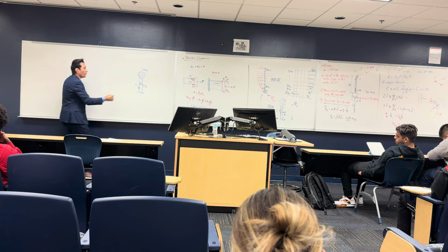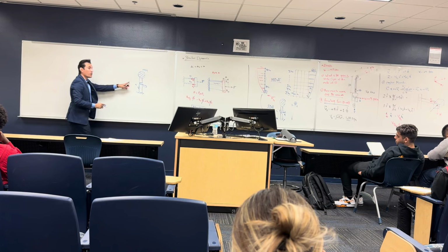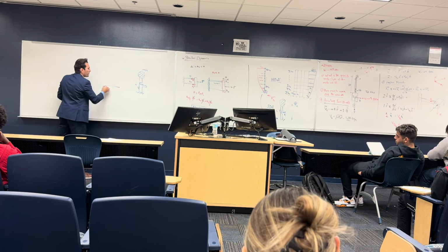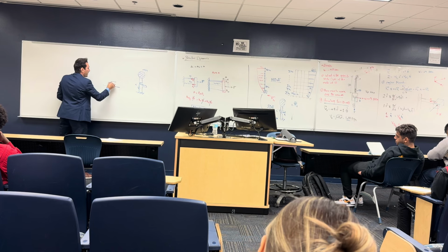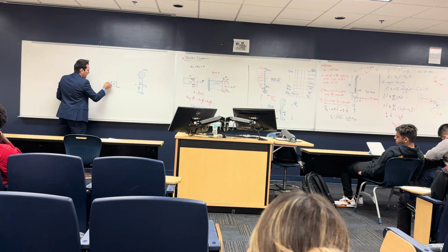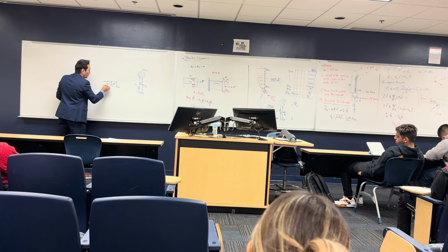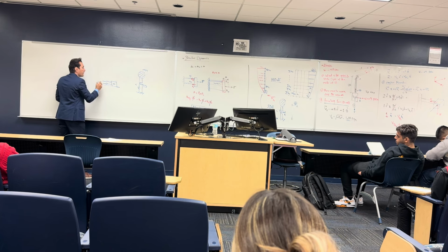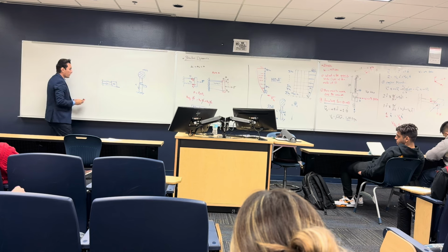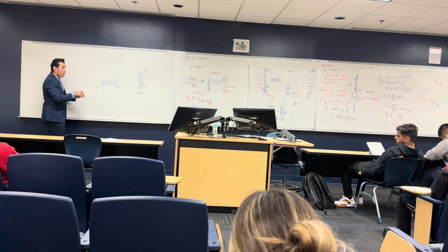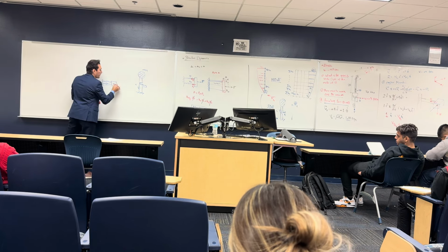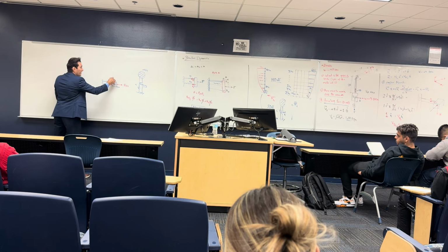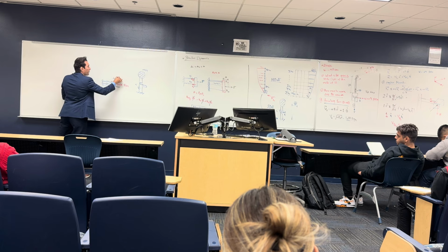So what I want to do, I want to get the equation of motion of this building. How? If we imagine that this building is like a mass, something like this, M, and it's attached to a spring this way, and also we call this dashpot, which means a damper. And after you apply an earthquake force, let's say, because the earthquake force is a force that varies over time, let's say F(t), this mass is gonna move this way.